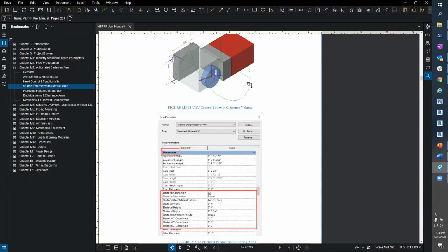Those specific systems have additional elements in there, such as electrical. So now, all of a sudden, when we're talking about a motor, we're putting together a motor list schedule because our VAV boxes and our air handling units and some of those different fixtures actually have electrical components in there. Now we have the ability to go through the manual, see some of that information and how it depicts into that motor list schedule and some of the information that actually pushes over there. Okay, so